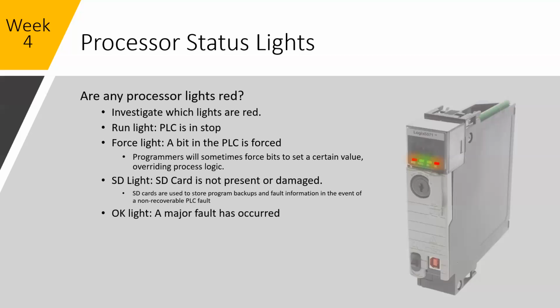And to load that SD card, you have to take your processor out of run mode. So if you're running a process that can never stop, and you can't put your processor into program mode to load that, it's not likely that people are going to keep backing it up. That's an aside.